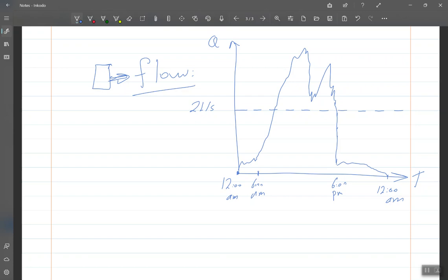So this should be the shape of the wastewater pattern that is produced by a certain house, and we can actually simplify that to a simpler shape, something like that. And what we actually give to the SWMM model is the shape of the red line.